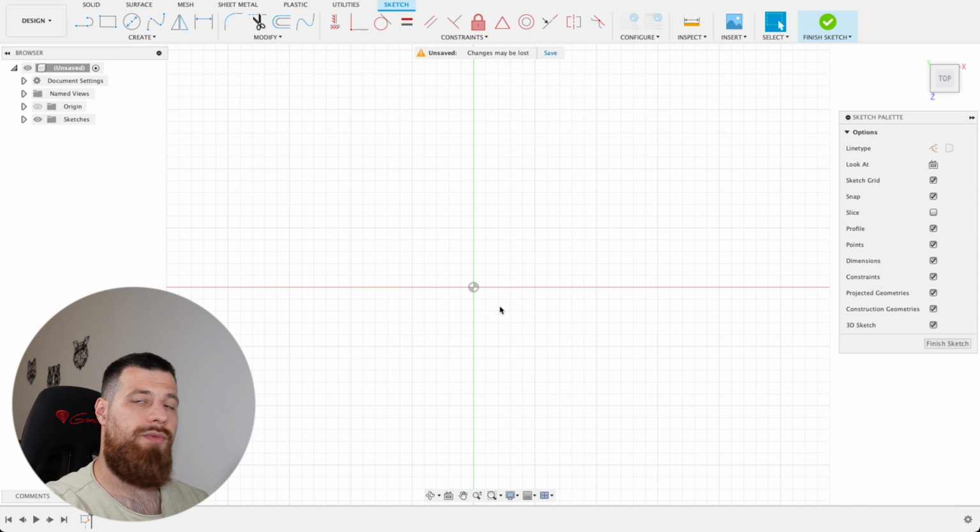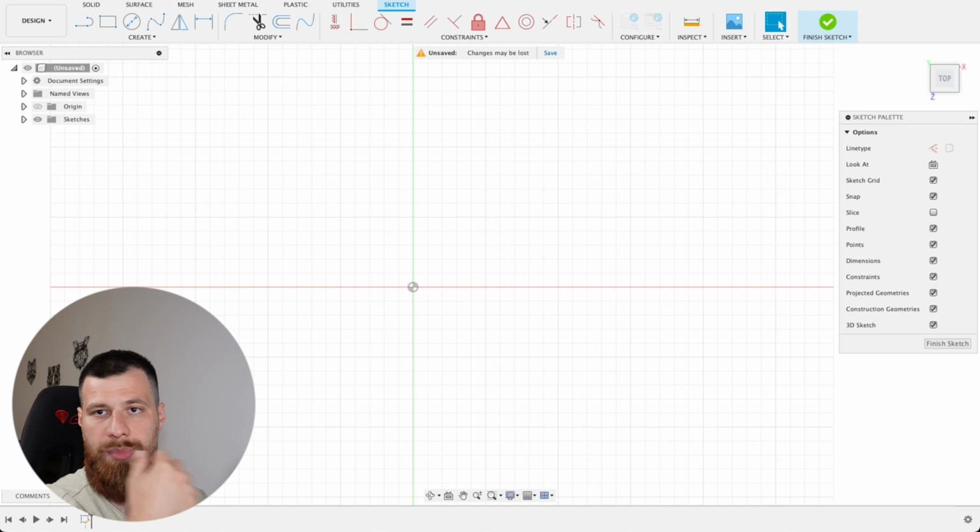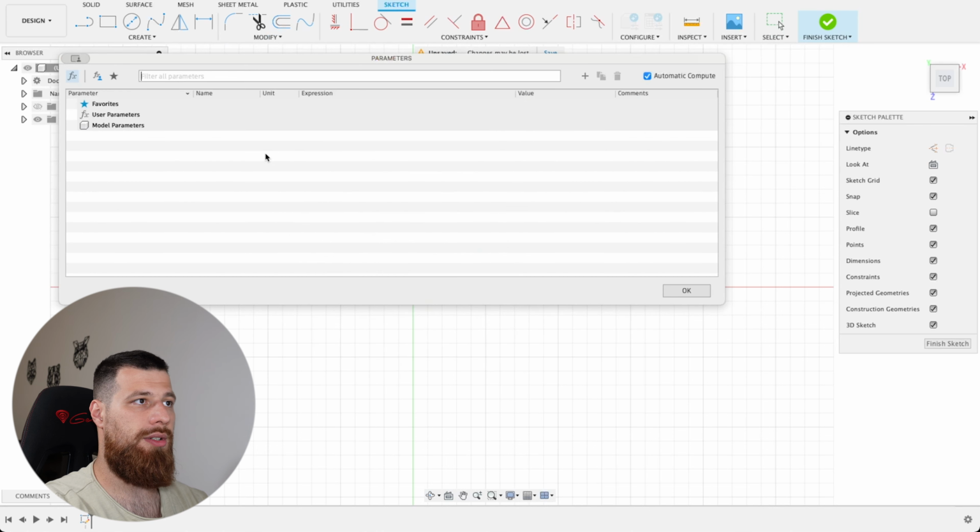Now, you first need to open up Fusion360 and we'll start with the basics. We should think about some design constraints from this point in time. What you want to create, you should think about it before starting Fusion360. For instance, in my case, I would like to create a 3D part that resembles a triangle that would be part of a larger assembly. This assembly will have interconnecting faces and should be parametric, mostly because I want it to be easily modifiable on the fly. So I can change some parameters, then export as STL, add some features, then export again as STL, and so on and so forth.